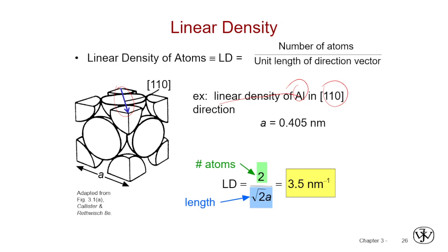So we should know that aluminum is of a BCC type. Last time I showed you that tabular column, right? Not BCC, sorry. What am I saying? This is FCC. Because if it's BCC, you will have one central atom over here. Here, it's all in the faces. So aluminum is FCC.